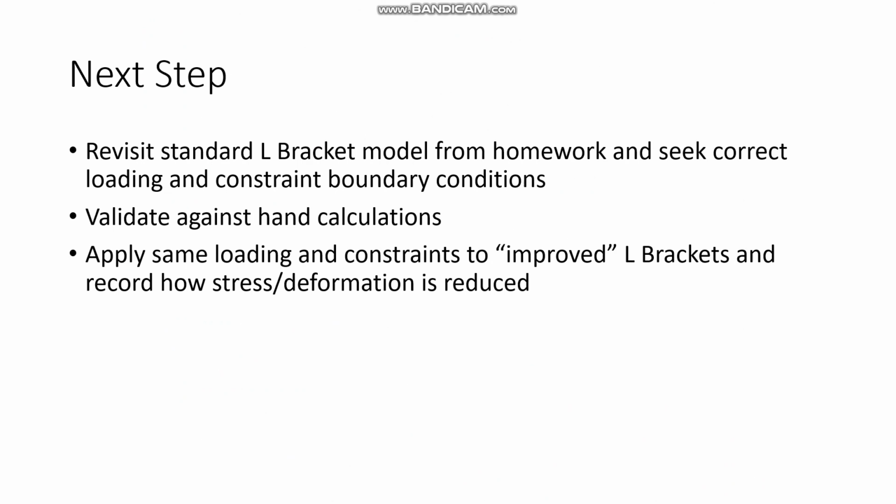In the next week, I plan on getting the basic L bracket model completed with improved boundary conditions and meshing. The stress will also be validated with hand calculations. Once the basic L bracket is modeled successfully, the other STL CAD files will be loaded into COMSOL and analyzed in the same manner, and the improvements will be found. And that's it.